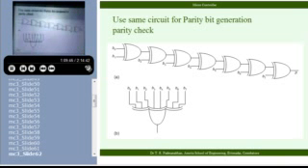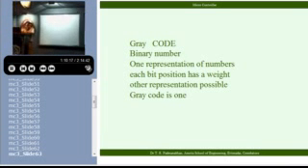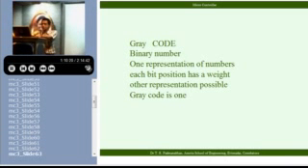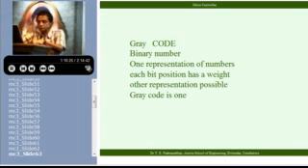Now, basically an exclusive gate is a 2-input gate. Multiple bits are XORed together, and this is a symbol used for a multi-bit XOR gate. It is essentially a set of 2-input XOR gates. So parity checking is done by repeated XOR operation. Earlier we discussed the decimal to BCD encoder, we did a parity encoder. Now I have taken one more encoder called a gray code encoder.